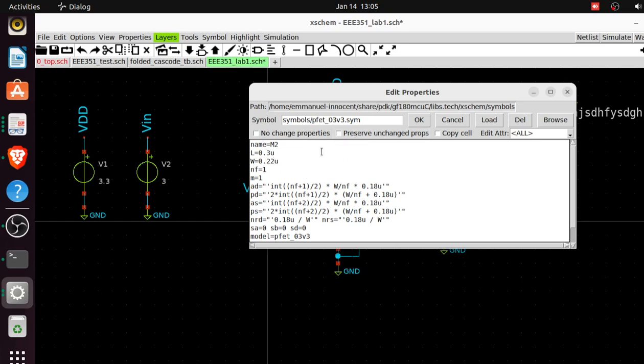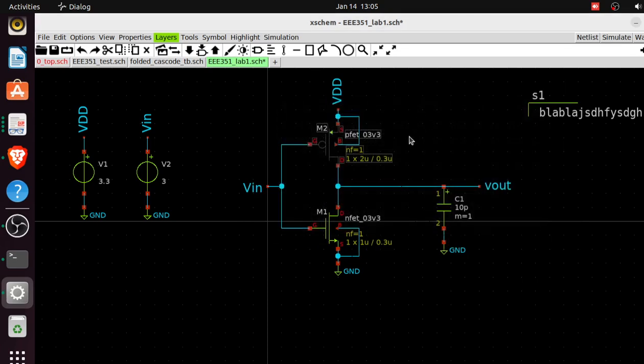Then the width, like we've said, the implication of those theories we've seen is that you make the width of the PMOS twice the width, or at least twice. You can make it thrice too. It was 1 there, so I can make it 2 micrometers. So we're done with the sizing here.